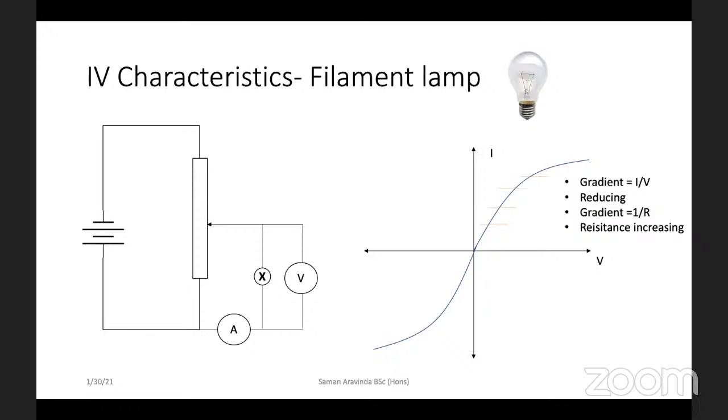So remember in advanced level, especially in unit 3, if they ask for a circuit diagram to be drawn for IV characteristic, that means to draw a conclusion of how potential difference affects the current, you don't use the variable resistor to draw the circuit. What circuit diagram should you use? This. Why do we not use the variable resistor? We can't vary the variable resistor so that the potential difference across the device is zero. So we can only do that by using what? This one, the rheostat, the potential divider.